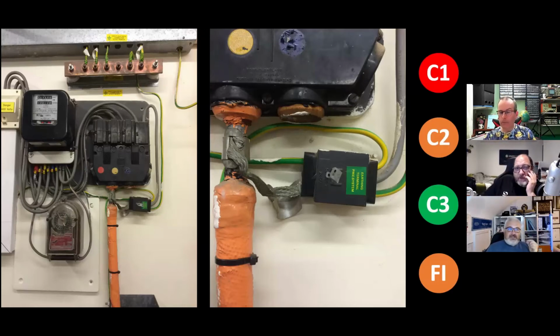So again, the configuration is almost in the competence of the jointer to a certain extent. Now, this is a perfect example to just talk to you about one little note. If you don't mind, I'm just going to read it out. There's a note in the UK Power Networks document, and it says replacing an older SNE network. So that is definitely an SNE network. It's an old PILC cable, separate neutral and earth, with a PME network, may lead to situations where customers would have an existing connection to a network earth terminal, which may no longer be appropriate on a PME network.